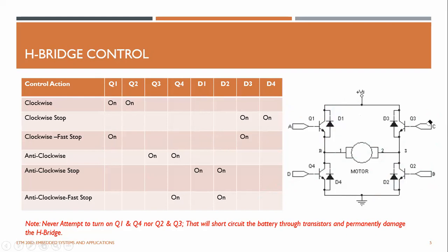And if you want to stop the motor, what you can do is just this is also 0 volt and this is also 0 volt. It was there, so this was at 5 volt, right? So if you turn off, you just put 0 volt here and 0 volt here, so this transistor will be turned off, right? So there's no longer current that can flow through there.